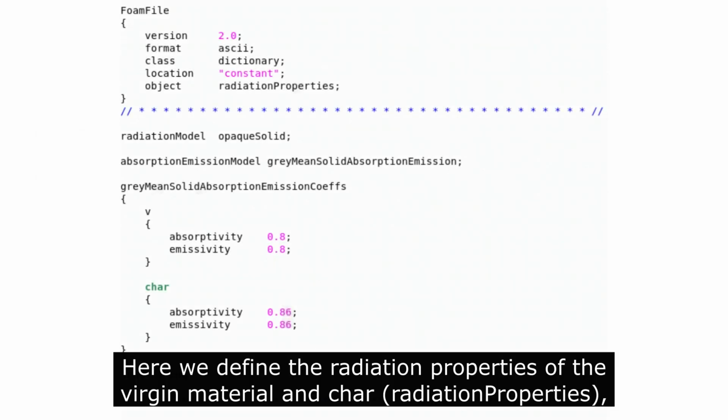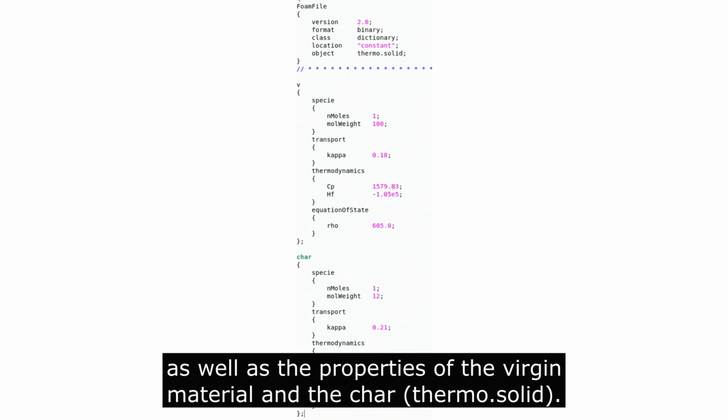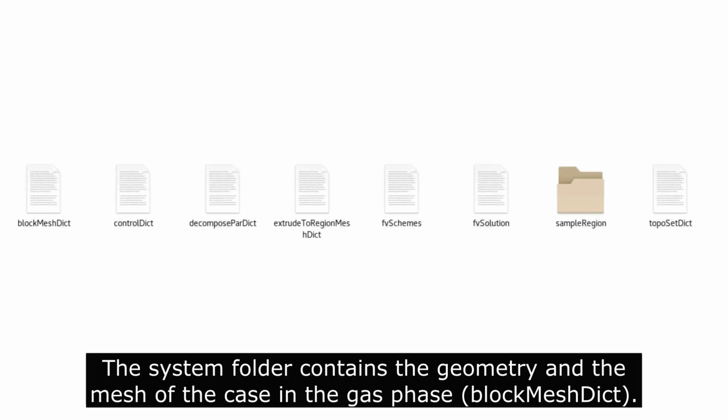Here we define the radiation properties of the virgin material and char, see Radiation Properties file, the Arrhenius decomposition reaction and its parameters, see Reactions file, as well as the properties of the virgin material and the char, see Thermosolid file. The system folder contains the geometry and the mesh of the case in the gas phase, see BlockMeshDict file.